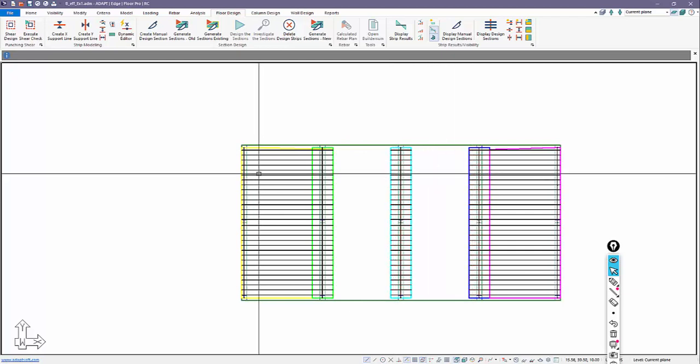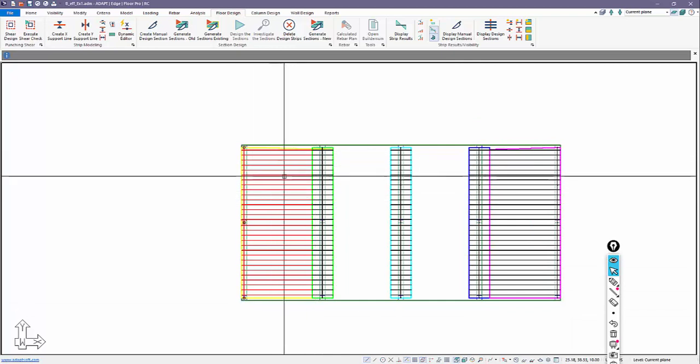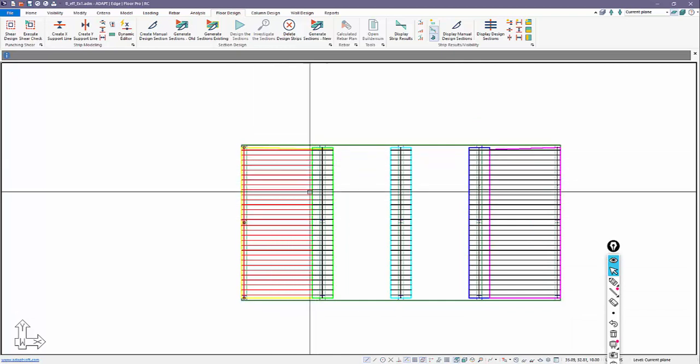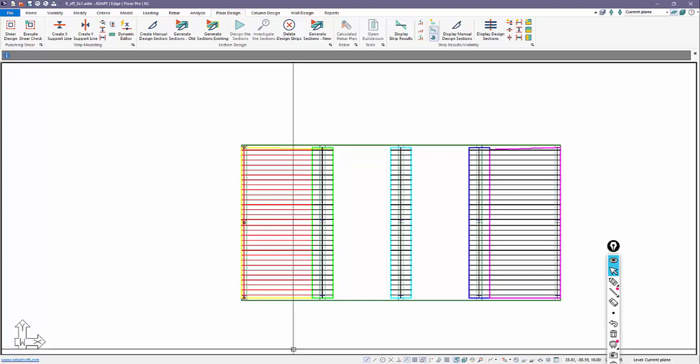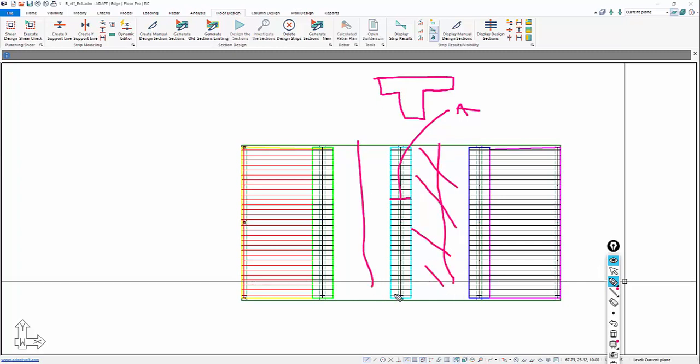We might also add something to the outside beams as well to avoid this completely extending over to this boundary for this tributary. This is another way to handle this. In this case, the program would again integrate only over the path of the design cut. Here you would get again actions, and we would design this shortened flange for those actions. You would still have this void that would have to be taken care of by additional strips.